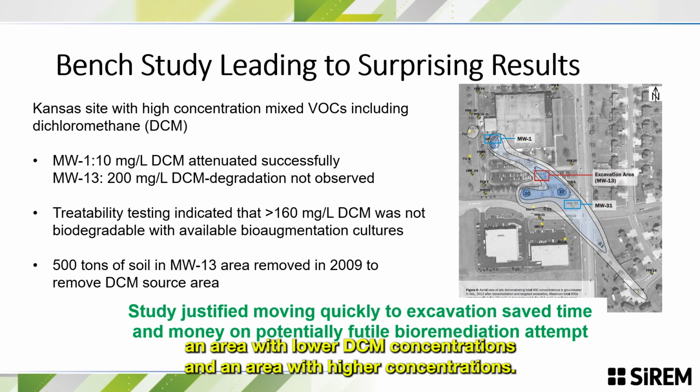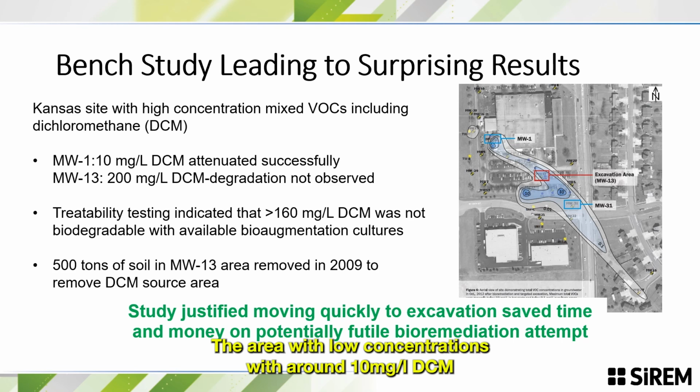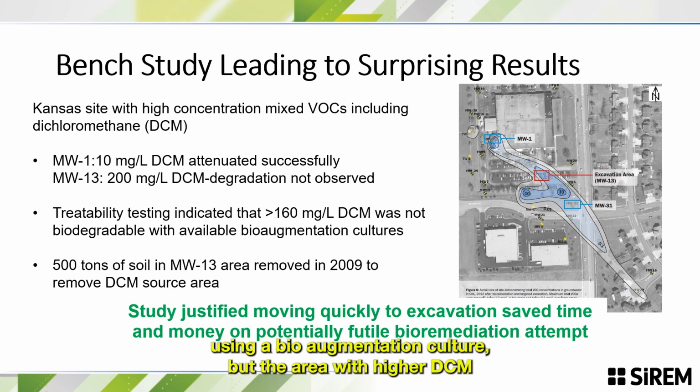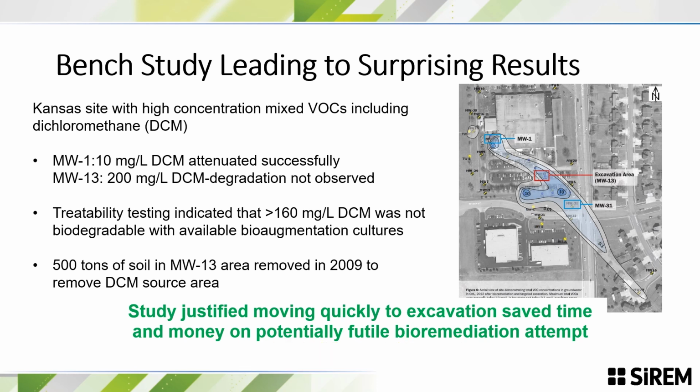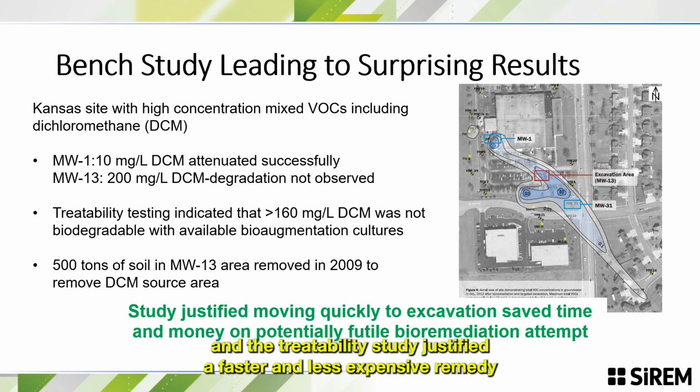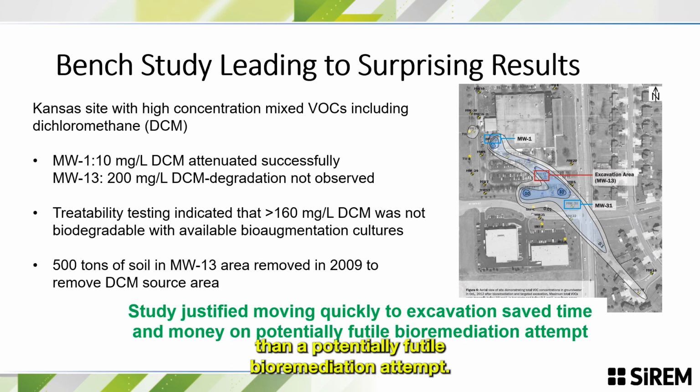The area with low concentrations, with around 10 milligrams per liter DCM, was able to demonstrate complete dechlorination using a bioaugmentation culture. But the area with higher DCM concentrations was not able to demonstrate bioaugmentation, and also demonstrated that DCM concentrations greater than 160 milligrams per liter would not be biodegradable with the currently available bioaugmentation cultures. As a result, excavation was selected as the remedial approach, and the treatability study justified a faster and less expensive remedy than a potentially futile bioremediation attempt.